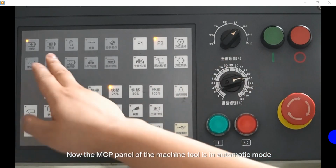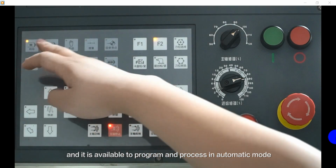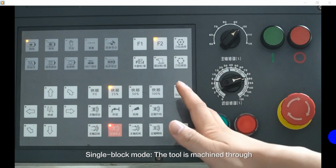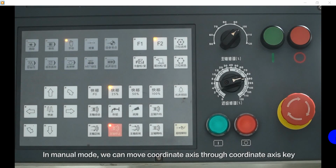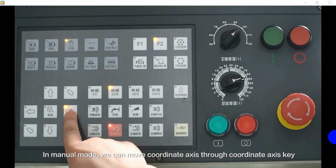Now the MCP panel of the machine tool is in automatic mode, and it is available to program and process in automatic mode. Single segment mode: the tool is machined through single segment operation when the program is running. In manual mode, we can move the coordinate axis through coordinate axis keys.